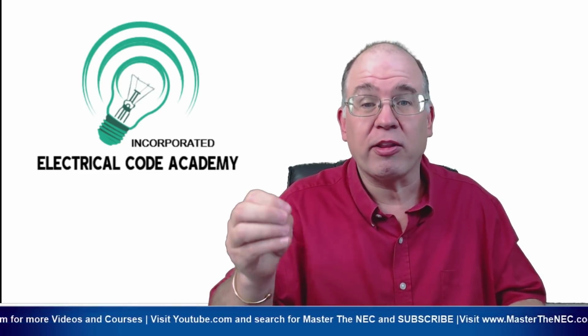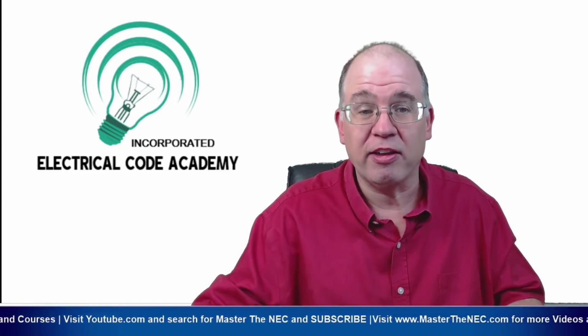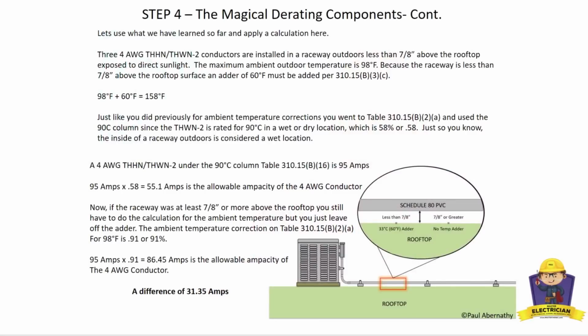Now they want to make sure that their 4 has enough ampacity after the application of this ambient correction and the adder that's applied. So we'll go back to this and look. In this case, we had a 4 gauge under the 90 degree C column in 310.15(B)(16). It's good for 95 amperes. And we could validate that, but we already know that's the case.